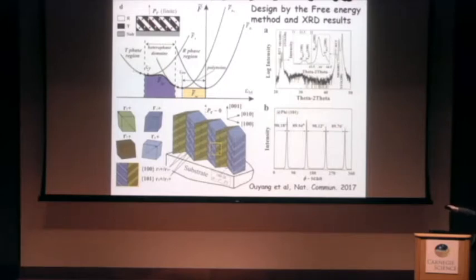In this case, you have a finite remnant polarization, but you probably can harvest a little bit more energy density, because when you apply the electric field, you're going to change one phase into the other. That costs you extra electric energy. But if you have a very thick film, you're going to have a dominant rhombohedral structure, hopefully, if we can have this hierarchical polydomain. So in this case, your apparent polarization is close to 0. And this polydomain structure can ideally have close to 100% charge-discharge efficiency, like I just described in the beginning.